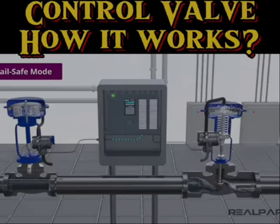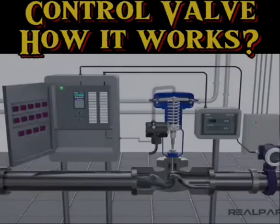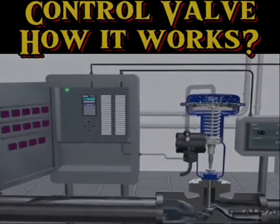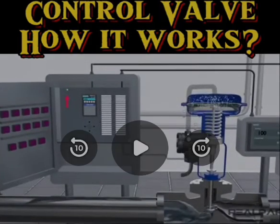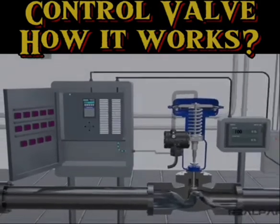The type of failsafe mode depends on the application for which the control valve is used. The actuator causes the valve to close in a fail-closed control valve. The actuator causes the valve to open in a fail-open control valve. In normal operation, the force of the spring must be overcome by the electrical or pneumatic actuator. In the event of a power failure to the actuator, the electrical or pneumatic force is no longer present, and the spring pressure forces the valve to open.